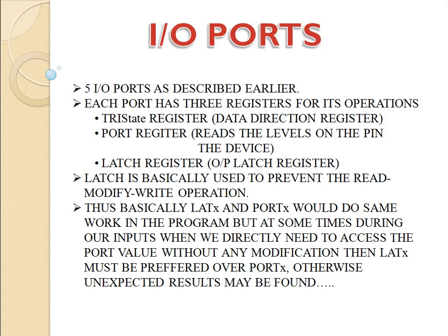Now the latch performs basically the same function as the port, but the only difference is that the latch doesn't perform the read, modify, write operation as the port does. So whenever we need to directly access the port value without modifying it, LATX is preferred to PORTX, otherwise unexpected results may be found.